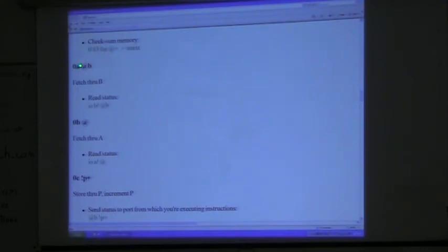Here's the same thing with the B register, fetch through B. It doesn't increment. For instance, if you want to read the status register, you stick the address IO in B. That's something that almost always resides in B anyway. And do a fetch B.